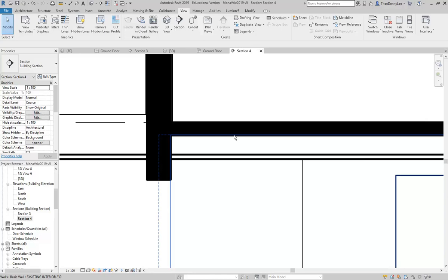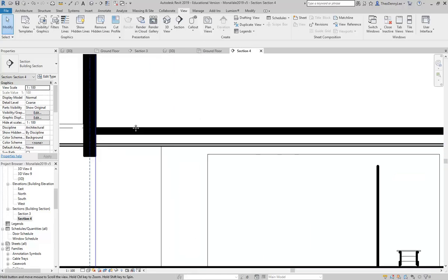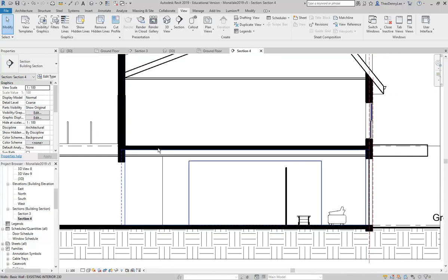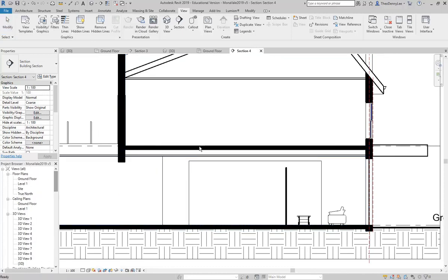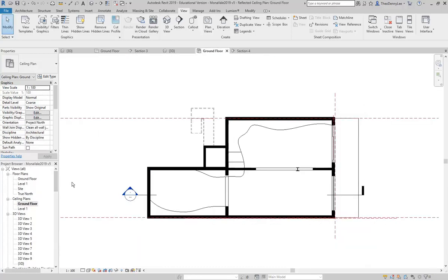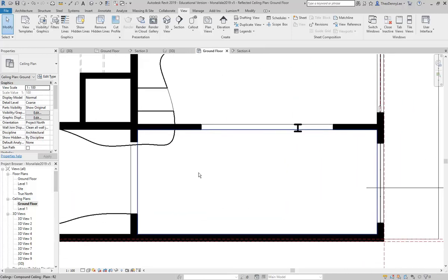What are the beams? Oh, the beams, okay. The way the floor structure works, it's good to think about that at the same time as you're making the ceiling. So the way the floor structure would work for a building like this would be, I'd say, to have the floor joists on the first floor spanning between this wall and that wall in the middle. Right, so that's a 4.6 metre span roughly? Yeah. And you can easily do that with a standard timber joist.